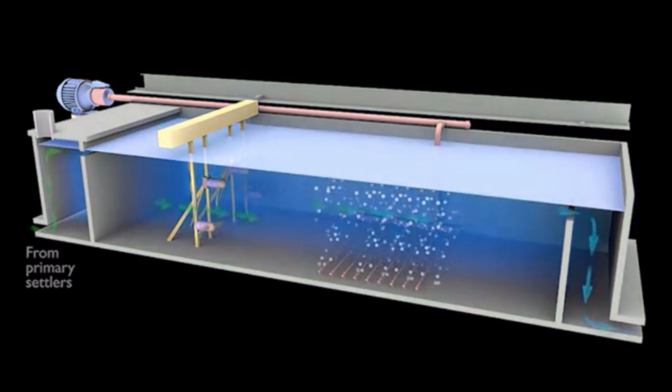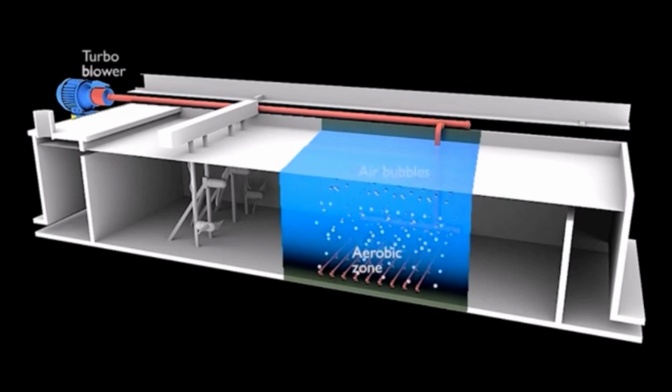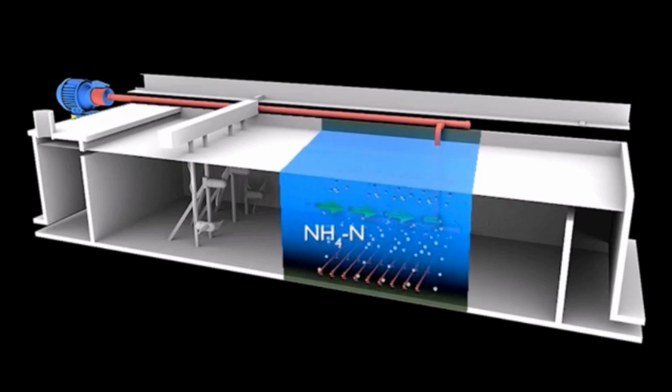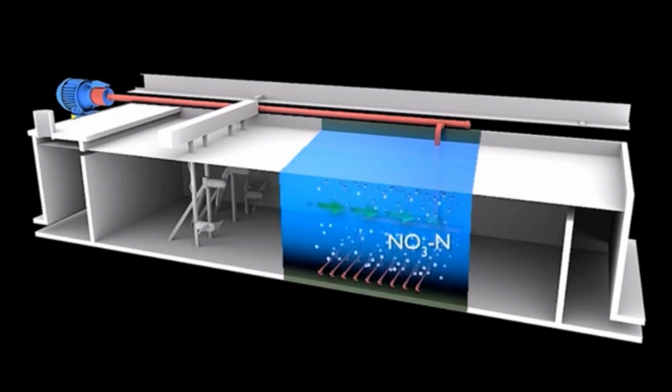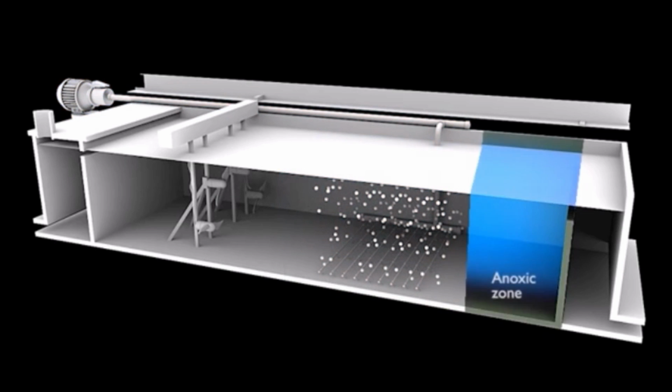During the aeration phase, wastewater is aerated in the aeration tank where air is pumped in, so specific bacteria will break down the dissolved organic matter and transform it into suspended solids. For example, some specific bacteria will oxidize ammonia into nitrate. During the non-aeration phase, also called the anoxic phase, which takes place in the anoxic zone, a type of bacteria converts nitrate into nitrogen gas, which is released into the atmosphere.